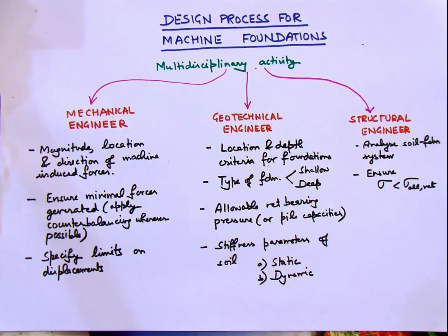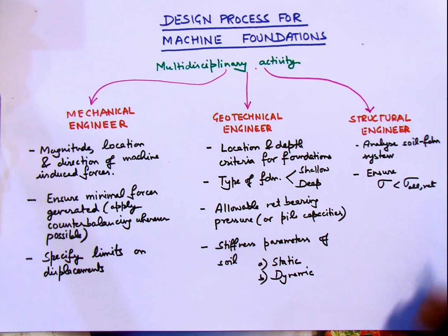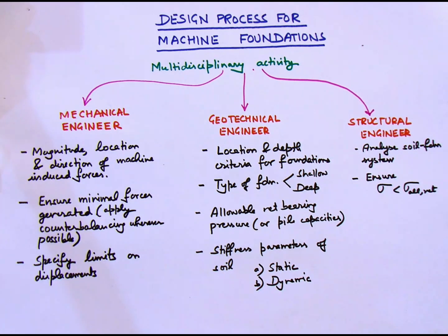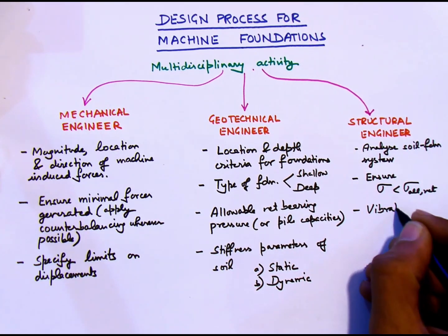So the stresses generated in the soil must be lower than the allowable net bearing pressure at any cost, and in case of pile foundations, the forces actually generated in the piles must be within the limit specified by the geotechnical engineer. Then the structural engineer must make sure that the vibrations are under limit.